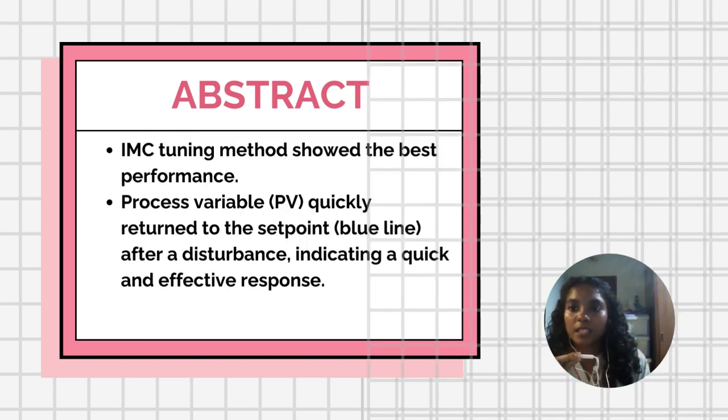Simulated gas mass flow process is selected for our experiment. In our experiment, we identify the process variable PV limits, set to 0%, which is MV maximum, and 100%, which is MV minimum, and the obtained PV values at 80% and 75% MV settings. Controller parameters were computed based on the Ziegler-Nichols method, Cohen-Coon method, and internal model control IMC method.